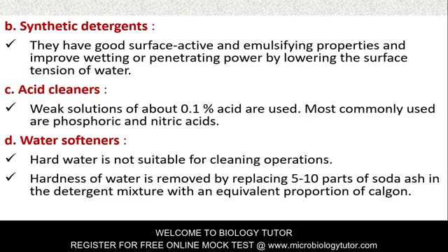Synthetic detergents. They have good surface active and emulsifying properties and improve wetting or penetrating power by lowering the surface tension of water. Acid cleaners. Weak solutions of about 0.1% acids are used over here. Most commonly used are phosphoric and nitric acids.